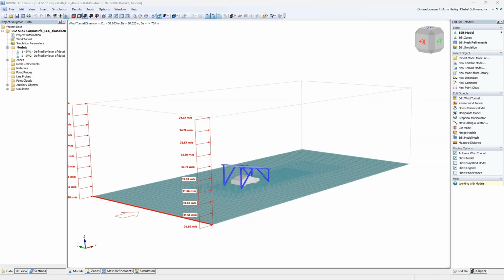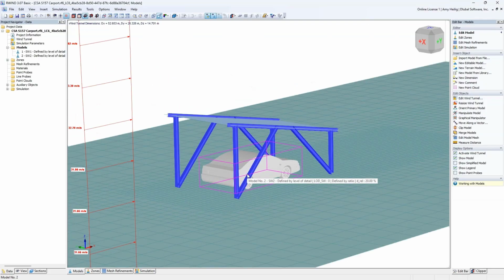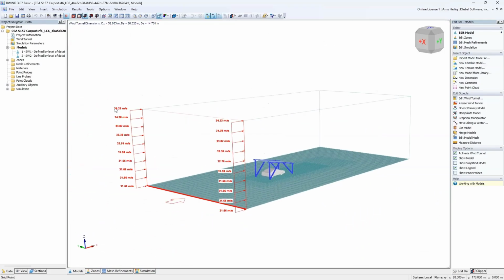And what I'm going to do is to actually jump into our wind directly. So you do have the ability to run this entire calculation silently in the background without ever leaving RFEM. Alternatively, we can go ahead and look at the RWIN model directly in this standalone program. And you'll see that this carport structure was automatically exported out to this numerical wind tunnel. We also have our IFC file considered here. We have our wind loads generated according to the NBC standard.